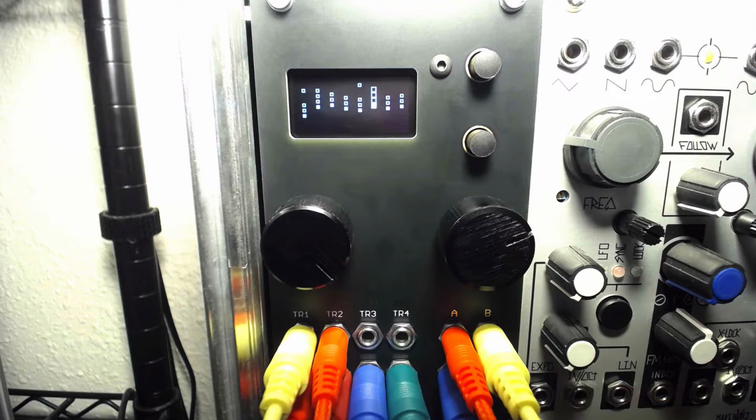As with many of the other modes, the CV inputs are assignable. Trigger 1 is the main clock, used to trigger chord sequences or quantize incoming pitch data. Trigger 2 can also be assigned to clock the chord sequences, while Trigger 3 switches between the different progressions. Trigger 4 resets the progression sequence.